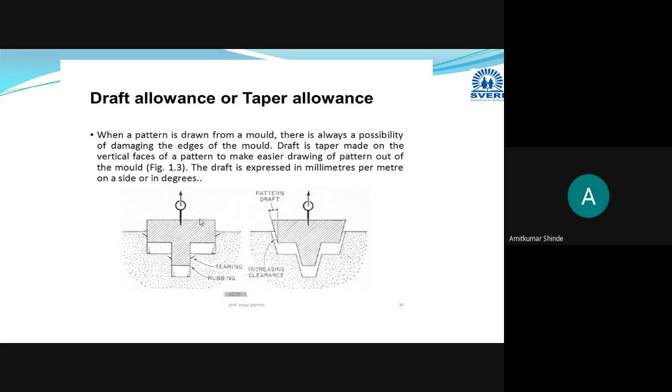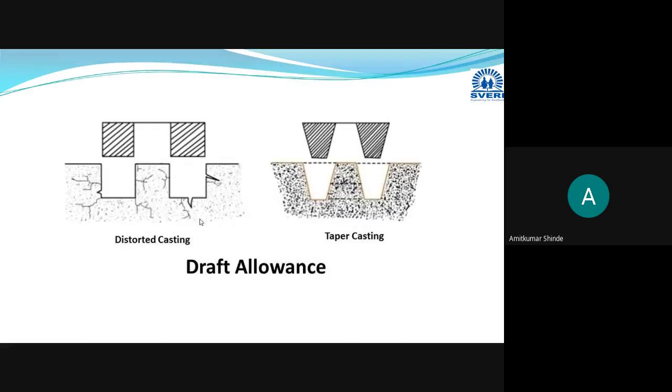For safe removal of the part, some taper or some draft is provided, that will be termed as draft allowance or taper allowance.